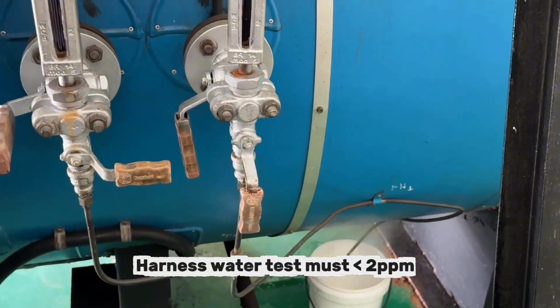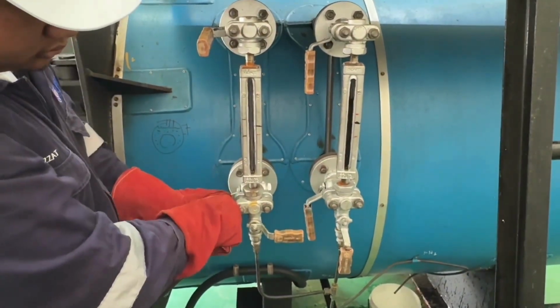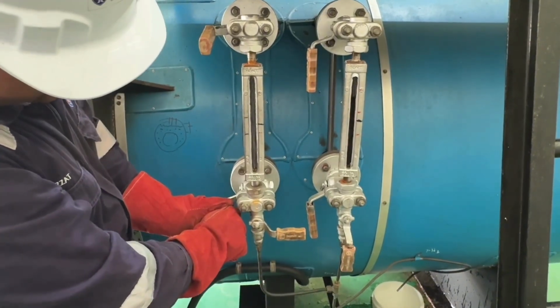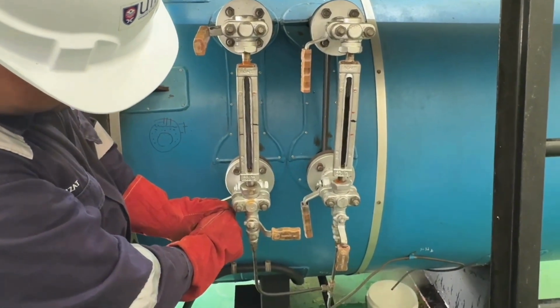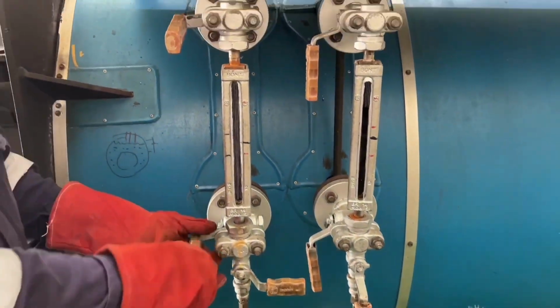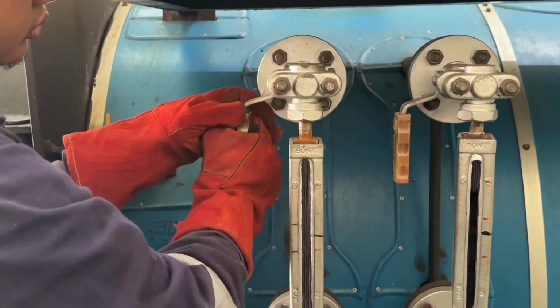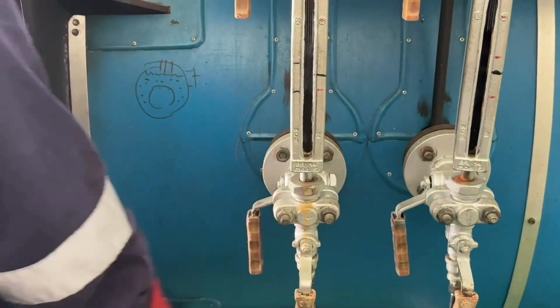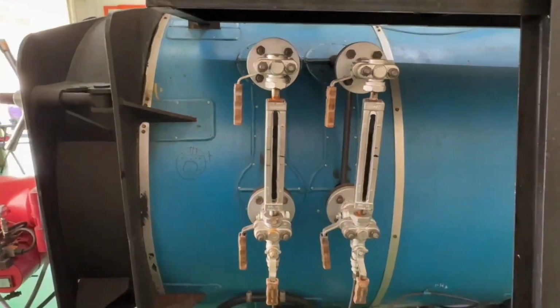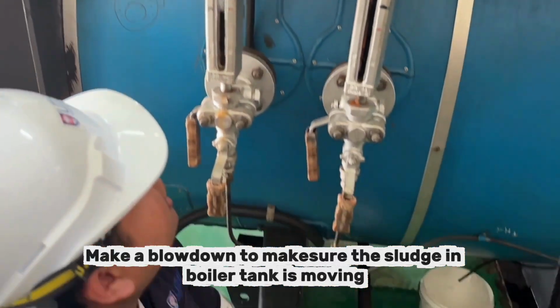The hardness water test must be 2 ppm. Make a blowdown to make sure the sludge in the boiler tank is moving.